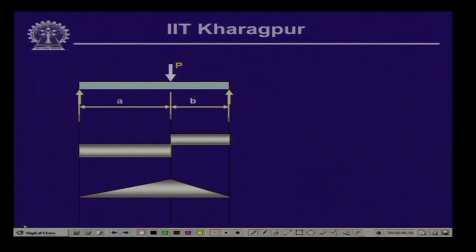You see, this is the shear force and bending moment diagram of this particular beam, which is loaded with the concentrated load P over the span L. If we have a concentrated load placed at a distance of a, we have the shear force variation. As we have seen, the shear force here is, I am sorry, negative over here, this is negative and this is positive. For the bending moment, as we have seen, it is positive for the whole region.